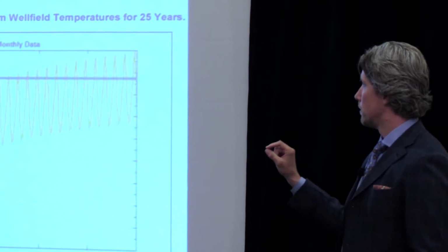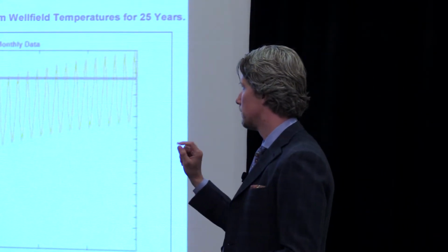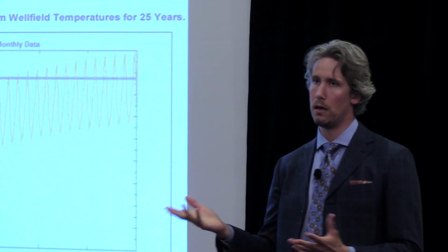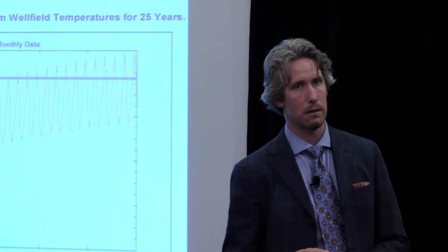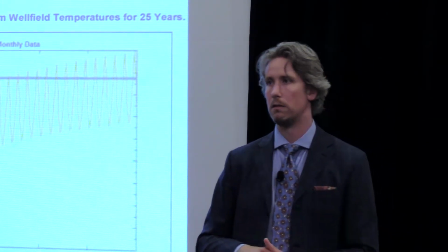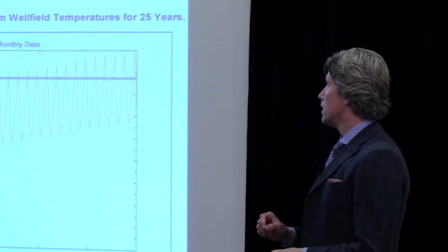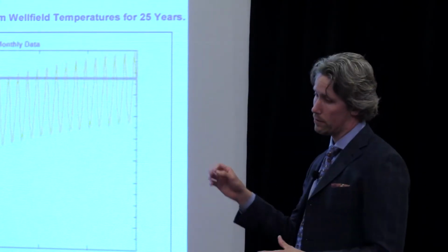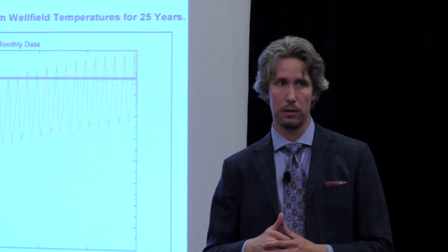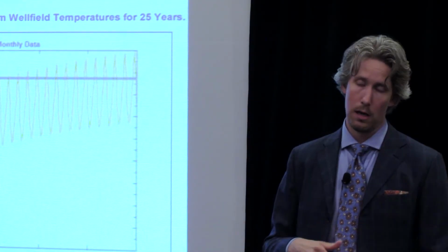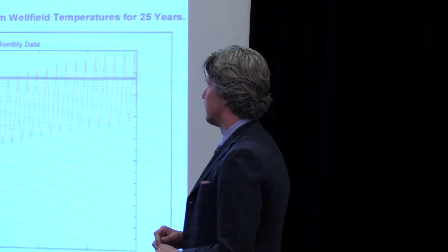In this particular building, the ground had heated up to the point where the heat pumps were starting to trip off. And the maintenance personnel was saying once that loop temp reaches 108 degrees, the heat pump compressor trips off because the water is too hot. So in the middle of this project, they were shutting portions of the building down and sending people home from work. It happened to be a city hall. So that was kind of a bad situation.